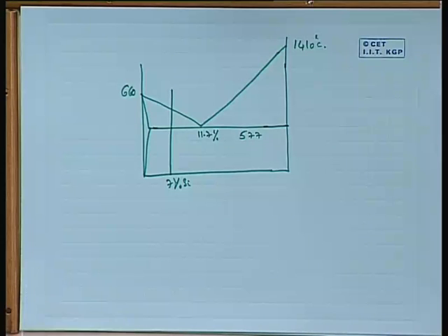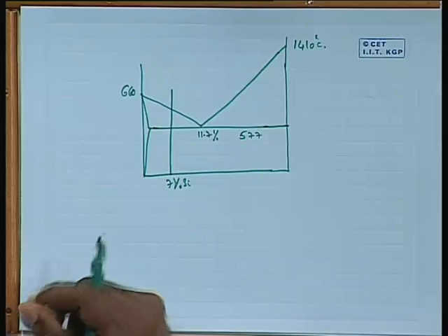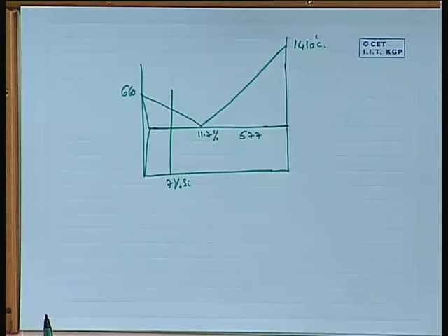We know that whenever the aspect ratio of a precipitate is very large, aspect ratio meaning the length to the diameter or the length to the width, then the tip of these particles acts as what is called a stress riser, and you will have a triaxial state of stress coming out there, because of which the material fails in a brittle manner. So you want to avoid such long needles in any microstructure.